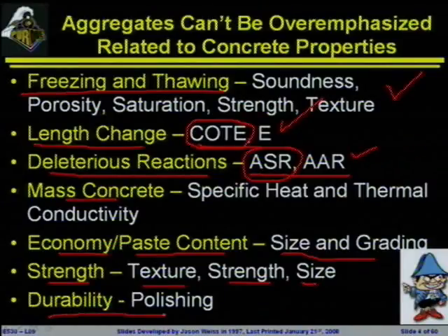And then sometimes you can get an aggregate surface that'll polish. So you'll put the concrete down, and then over time the concrete will start to become slippery, because the aggregates will be polishing under, either stopping traffic or something like that. And it's a real big problem when you start to look at traffic safety. So you want to make sure that your aggregates don't polish, don't become slippery. And this is a big important thing to look at.